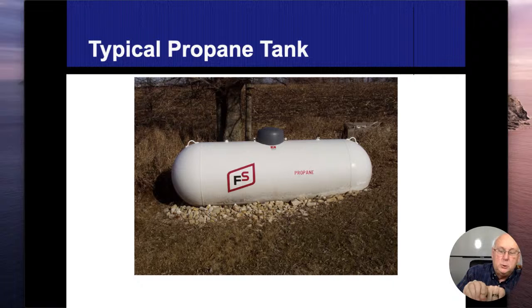So where the gas shoots out before it pulls in the oxygen and mixes with it, the propane orifices, because they're more flammable, they're under a higher pressure, those are going to be smaller. They're going to limit the amount of fuel that's going to shoot out of there. The gas orifices are going to be bigger so that more fuel can come out of there. I have heard of that as being a test question, but if somebody says they put their grill on natural gas and now they don't get any heat, that's the reason. The orifices are too small.